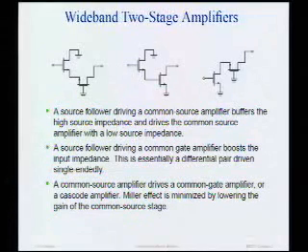All right. Another way to build a useful two-stage amplifier is basically, one of the big problems with our common source amplifier was the Miller effect, right? And we mentioned that if you have a low source impedance, Miller effects may be not too bad. Well, one way to generate a low source impedance is just to buffer the actual source impedance.